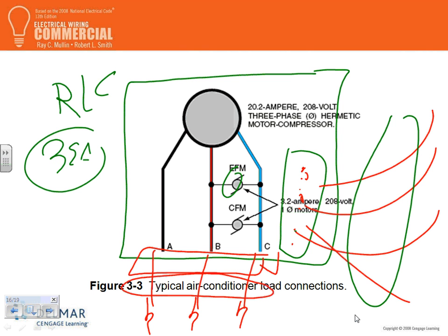What they do most of the time is they pull information from this controller, I don't want to go there, into a building automation system, and right there they control the whole system. If you have multiple chillers, pull all this information to the building automation system, and that's how you turn the chiller on and off, and turn the boiler a little bit on to compensate and so forth. Any questions about that? But our interest really is wiring this equipment or sizing the equipment.